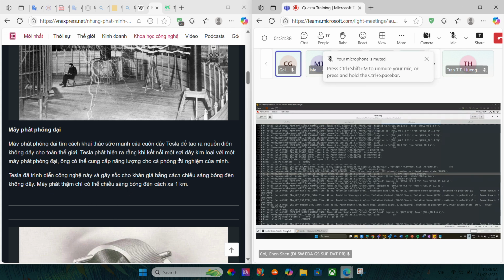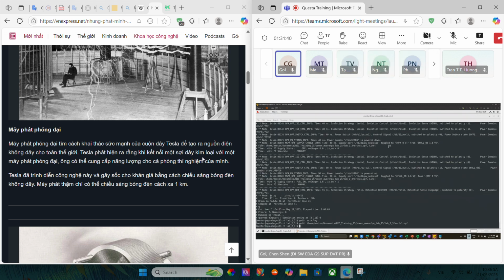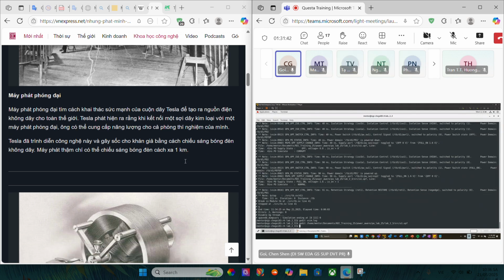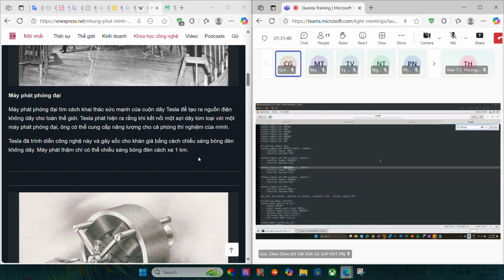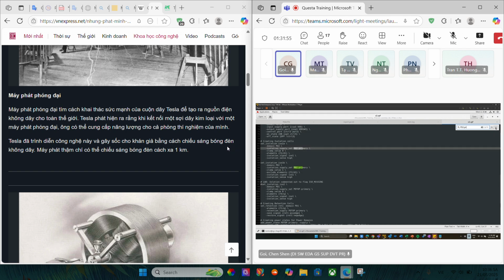So let's search for PD2 in the UPF, pd2.primary. PD2 primary is a supply set. So we created this supply set and then let's see further down what we have for this PD2.